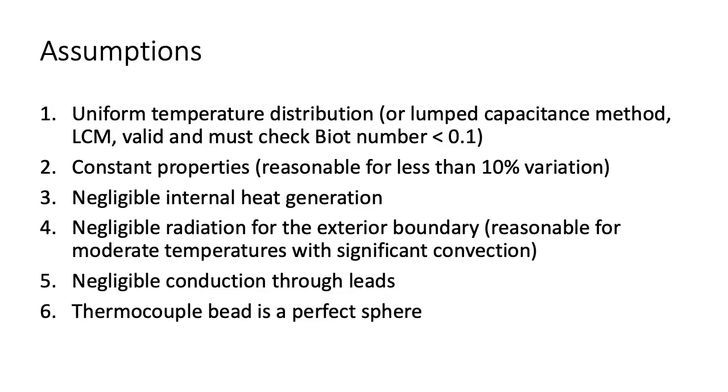Our third assumption is that there is negligible internal heat generation, which is reasonable for a thermocouple with very small currents. Our fourth assumption for this problem is negligible radiation for the exterior boundary. This is a reasonable assumption for an opaque wall and for moderate temperatures combined with significant convection at the exterior boundary. Our fifth assumption is negligible conduction through the lead wires for the thermocouple, which is reasonable since they are probably at a similar temperature as the bead.